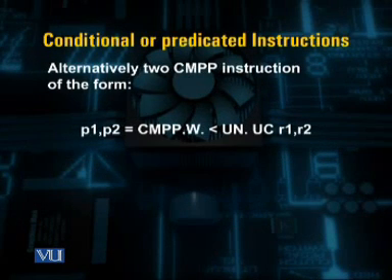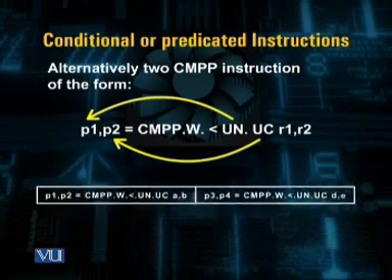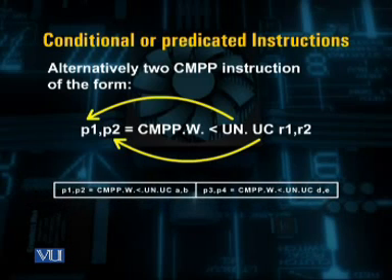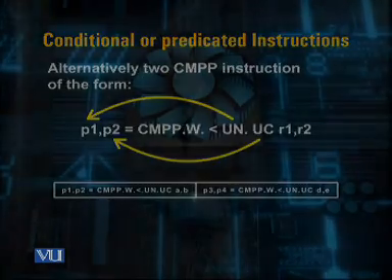You can see this from this example statement where P1, P2 is updated with the help of one compare operation for the condition to be true and the condition to be not true for the values contained in registers R1, R2. This way the very long instruction word for the two if blocks can contain only two compare instructions instead of 4 as in the first case.